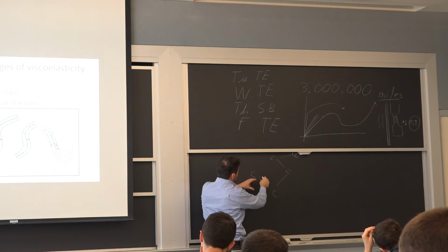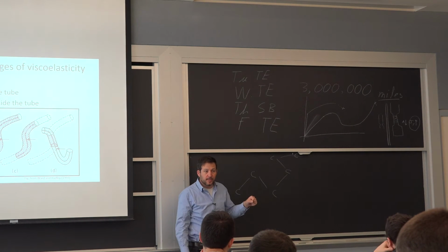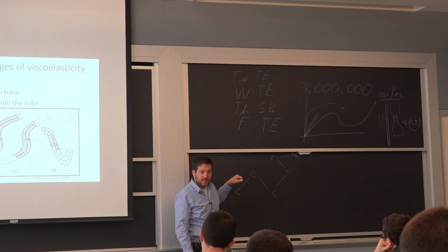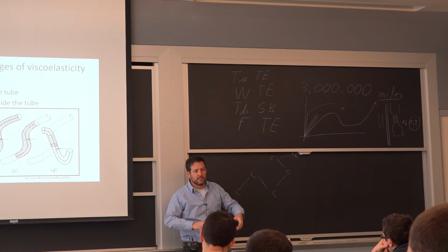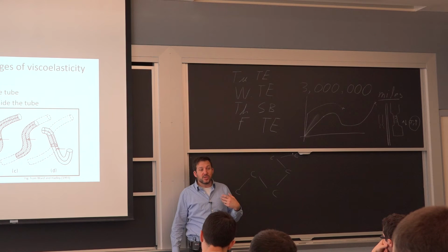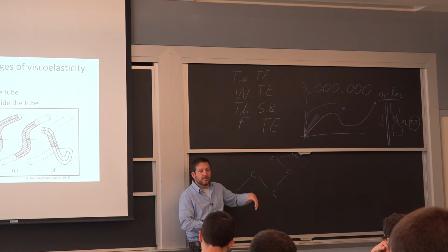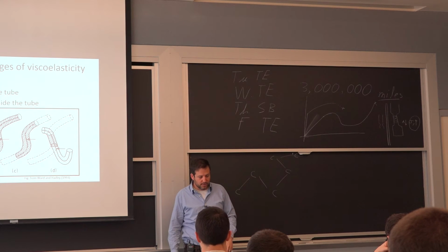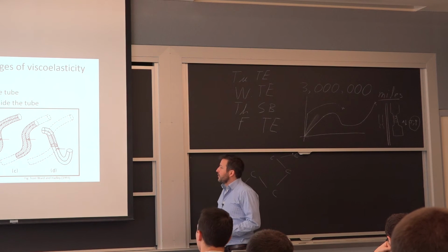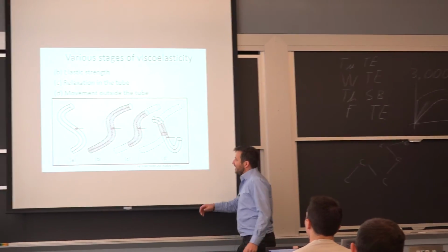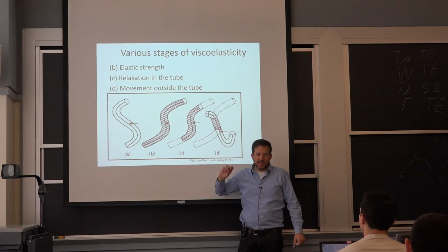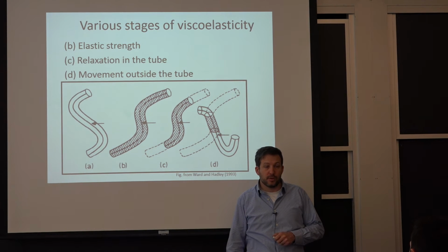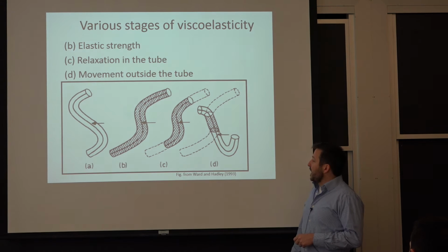So you can just rotate this because we're not talking about changing the angle of these connections nor the distance. It's just about twisting it. So just by twisting it, it happens very, very quickly because all these movements are very, very quick at the junction between individual connections. So you get that behavior very quickly. So the elasticity in the case of the plastic is not the stretching of the bonds, which is the case with metals. All right, what happened next?